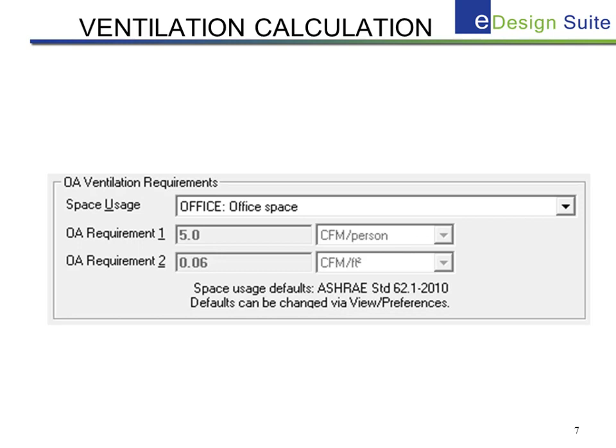Ventilation is the outdoor air load. The ASHRAE 62.1 ventilation rate procedure analysis is integrated in the HAP program. You simply pull down the type of space, it does the rest with all the required ASHRAE 62.1 corrections.